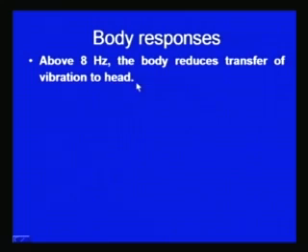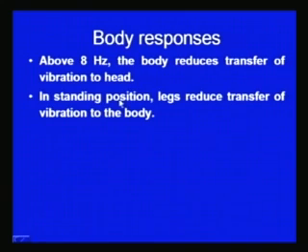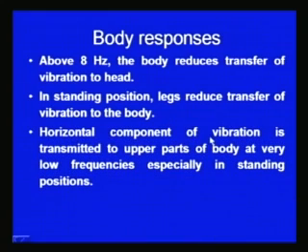Above 8 hertz, the body reduces the transfer of vibrations to the head, and in the standing position the legs reduce the transfer of vibrations to the body. But the horizontal component of the vibration is transmitted to the upper part of the body at very low frequencies, especially in a standing position. So, in a standing position, the transfer of vibrations to the body is reduced, but the horizontal component of the vibration is transmitted to the body.